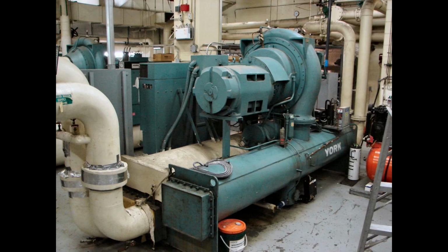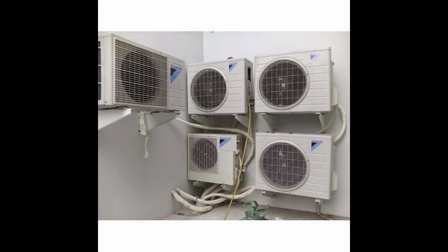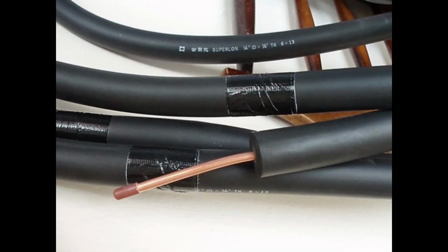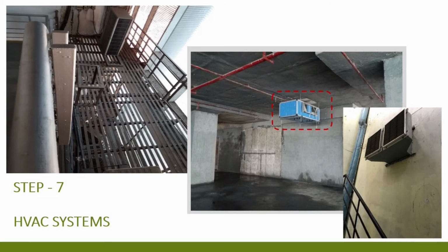provides. Also checking the location of outdoor units if required to be placed, understanding the feasibility of running copper pipes and the ventilation provided in the area. The fresh air intake and exhaust provisions provided at the site need to be documented as well.